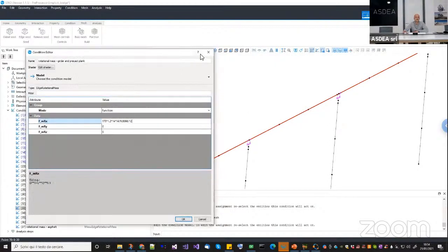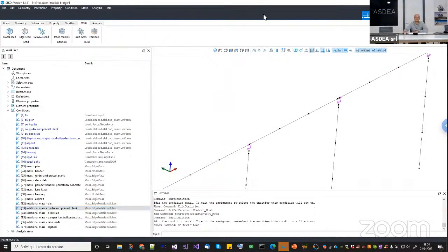Why? Well, basically because, let me try to do an annotation here. If you remember, we have a cross-section that is quite thick, something like this, okay? And of course it extends all over. If I model this one as shells, then I would have many nodes along the width of the slab.